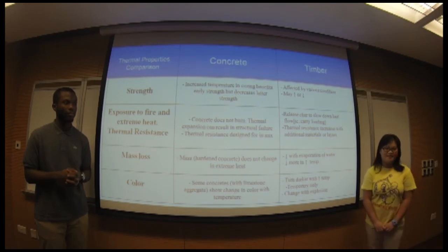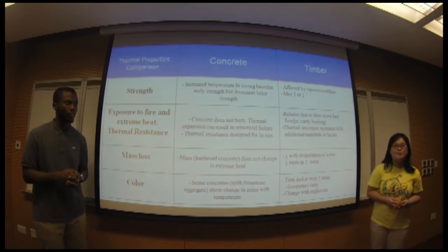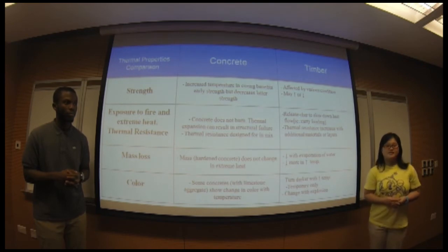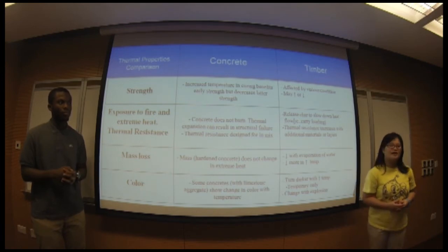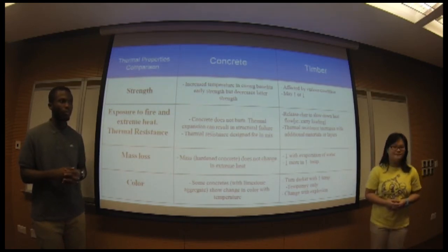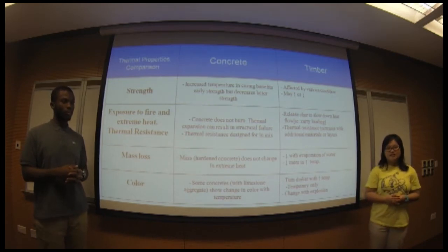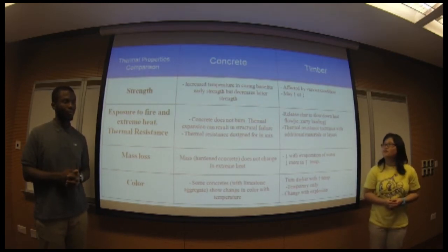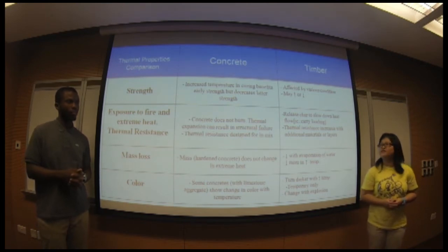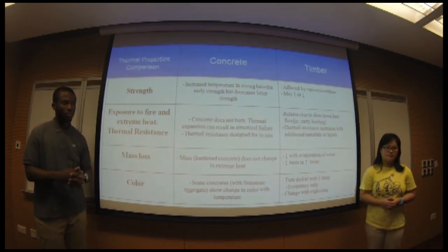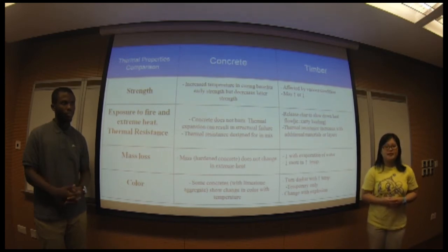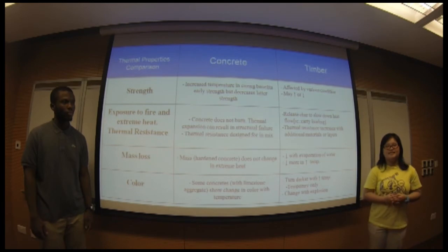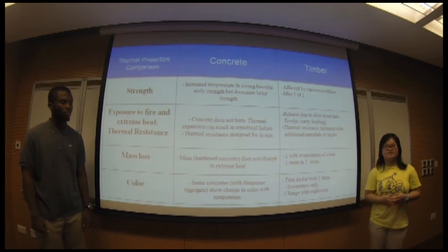Timber does burn. However, the thermal resistance of timber is determined by itself, which is the release of char. Releasing char can slow down the heat flow. In a structural building, a large dimension timber can still carry loading because the heat flow is slowed down by the char, and this helps prevent losing a high mass weight, and this helps the timber to resist loading.